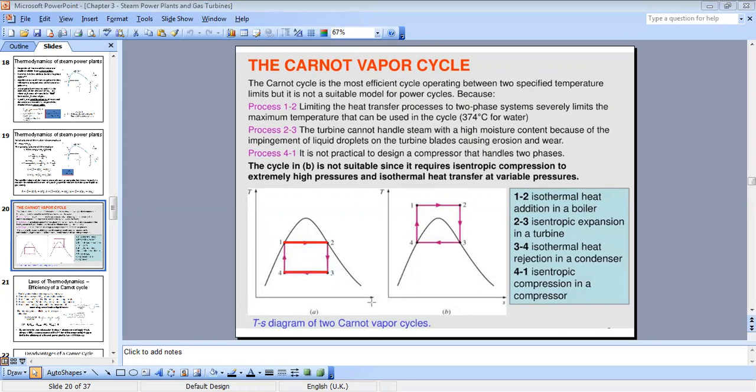So when I say constant entropy S, this means that these are adiabatic processes, so I don't have loss of energy during these processes. Okay, so now let us see what are these phases. Now, for example, if I want to talk about a power cycle, what is my purpose? My purpose is to produce a certain work.